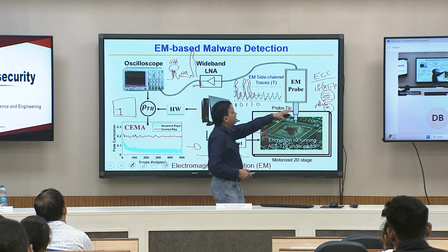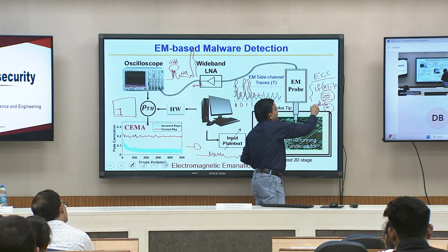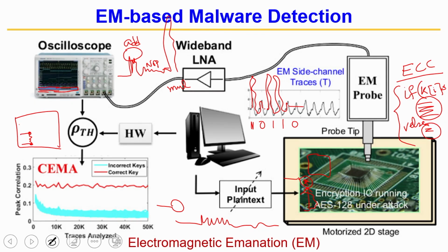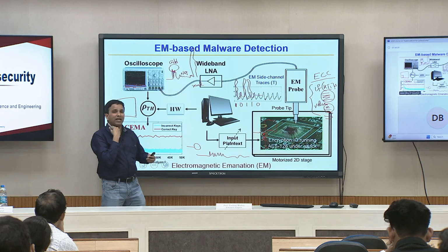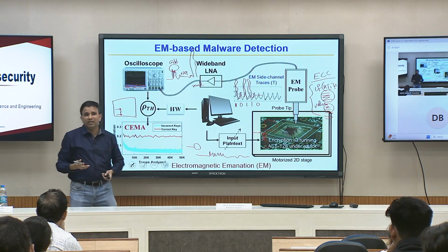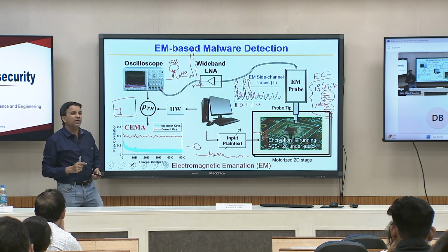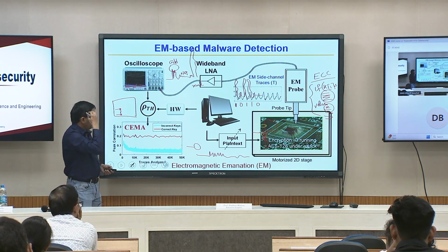So, since I am talking about this, does anybody know what the solution for this is? What is the solution people use today? It is called masking. The only reason I am able to figure this out is because this is imbalanced. If statement has more instructions, else statement has fewer instructions. I will put a bunch of garbage instructions just to match this one, so that the power profile becomes exactly the same. But the problem is you are unnecessarily introducing power consumption. Instead of going for a power efficient solution, you are going for a power inefficient solution, right.